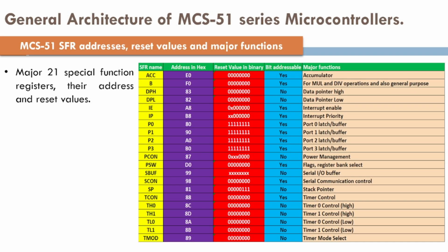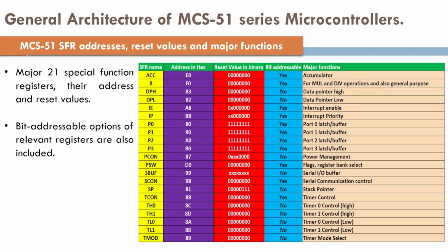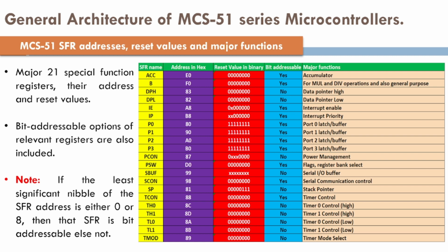It is important to note that if the least significant nibble of a special function register address is either 0 or 8, then that SFR is bit addressable, otherwise, it is not.